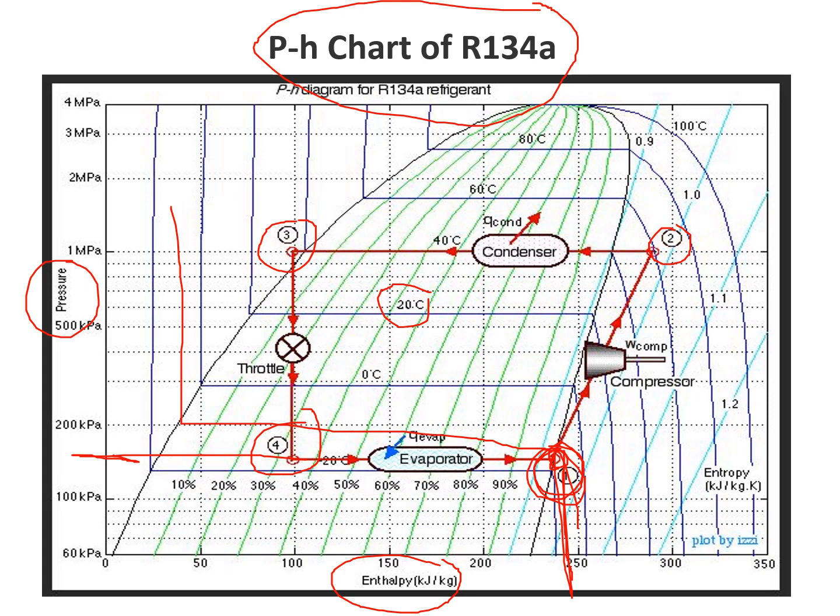Now we have the compression, that is isentropic compression. So you see these blue lines. These are the constant entropy lines actually. So now you have to follow the constant entropy line, okay, till the condenser pressure.